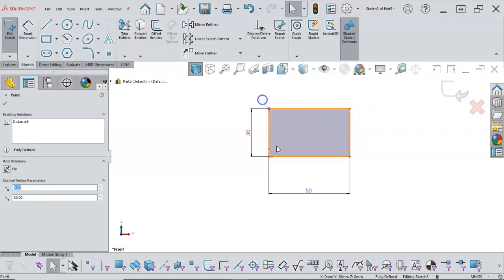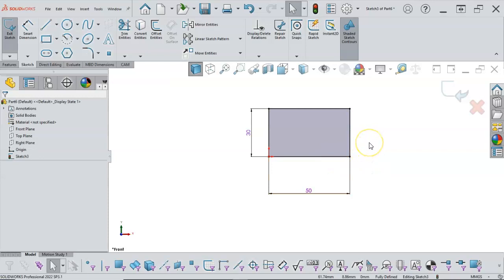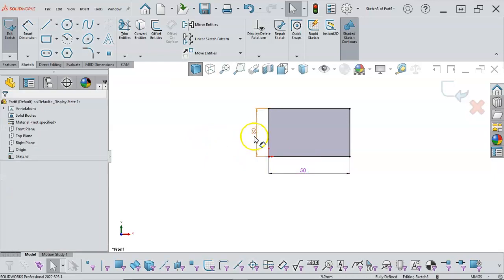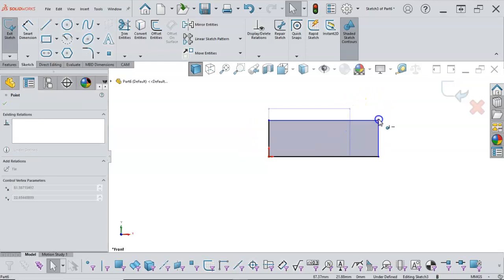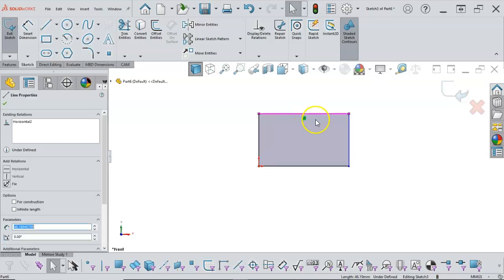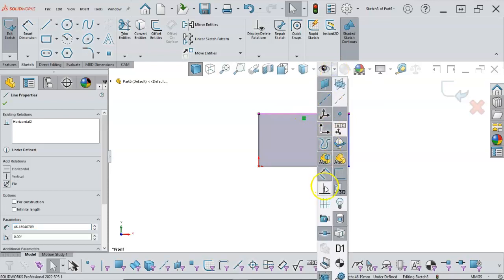Nothing moves accidentally. If I grab onto it and try to drag it, it's all going to stay in position. If I want to reposition my dimensions, then we can move those into place. All right, so let's say I get rid of my 2 dimensions. I just highlighted each of those and hit delete on the keyboard. Now we're back into a situation where this will drag, it will change directions, it will move according to the relations. All right, so the little green boxes, I think I turned that off, so yep, there we go.